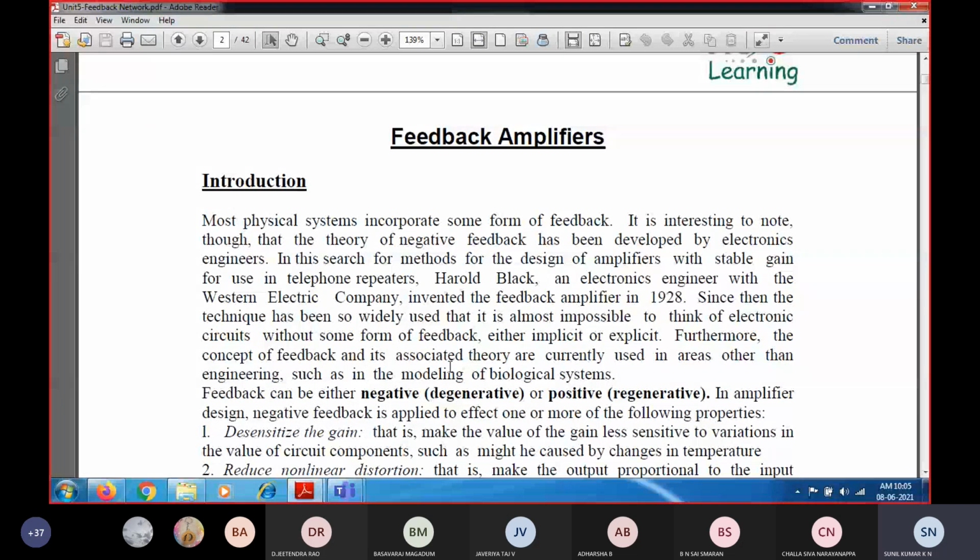So for a given set of input, if you apply small signals, the amplifier is going to give a large amplification, provided that the biasing of the circuit is maintained constant. As long as the biasing does not have any issues, you will have the maximum amplification. That was what we saw in the first module, and we overcame those biasing network problems.